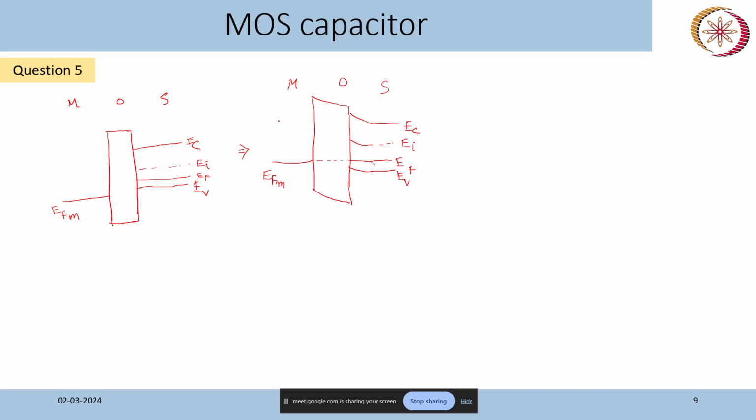For example here, if there is an electron at this point, because of the energy bands here, it will move like this. Because the direction of the movement of an electron and the direction of an electric field are opposite, there is an electric field in this direction. So whenever you see there is band bending, there is an electric field.